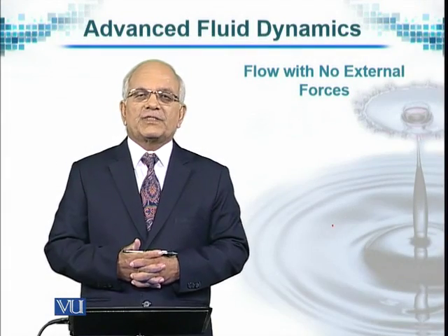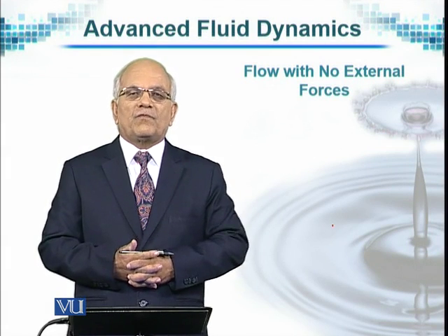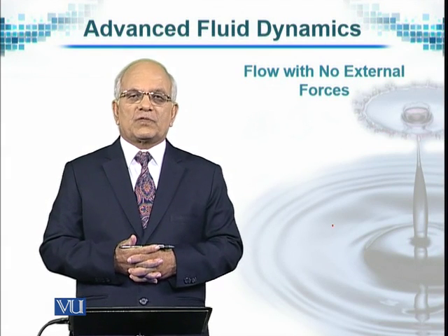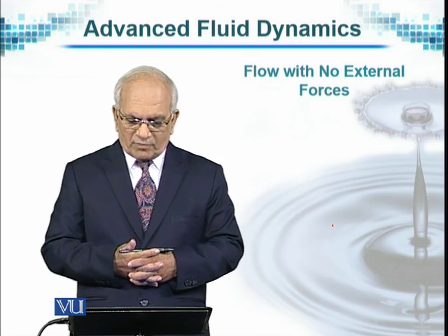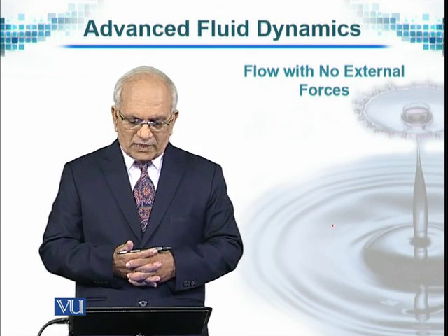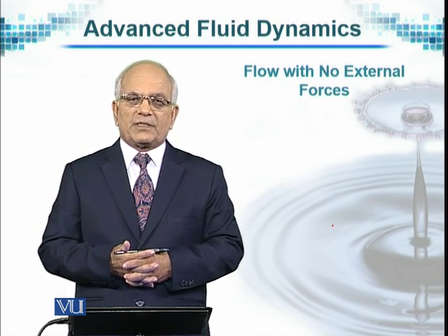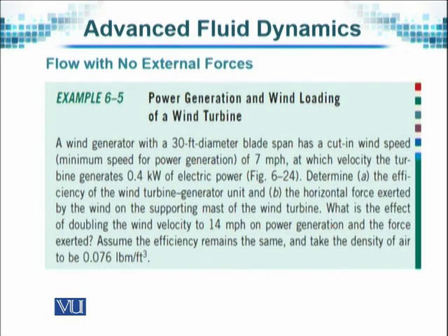Again, now consider another type of example in which we see the flow field with no external forces occurring, and we try to apply the momentum flux, rate of change of momentum flux equation, and try to balance the forces that are there. And in this case, the exercise is of a different type, and it is to generate power by using wind.